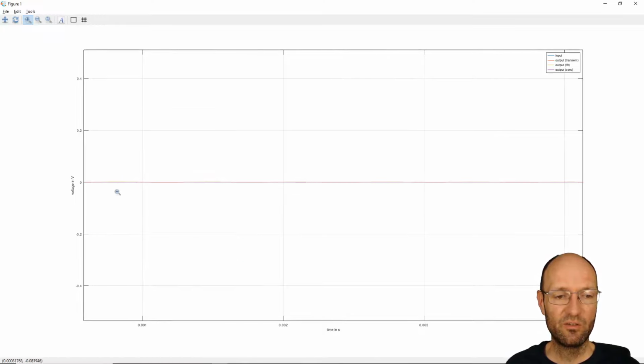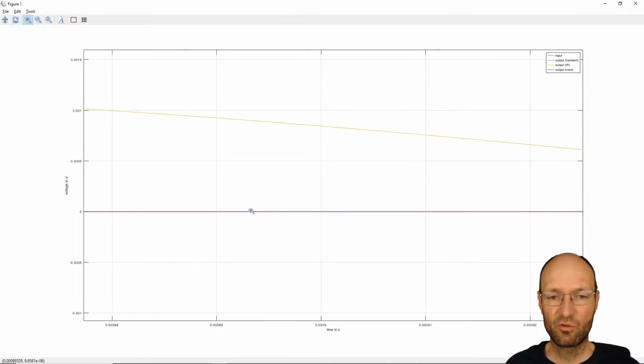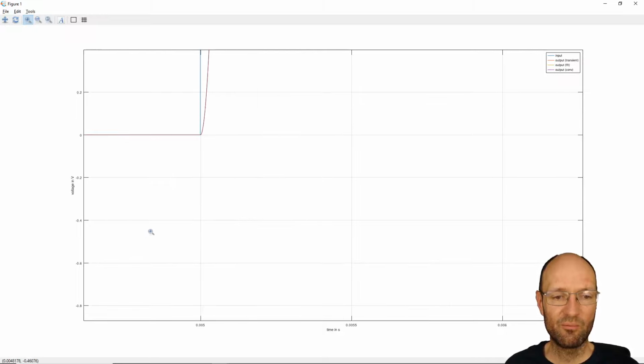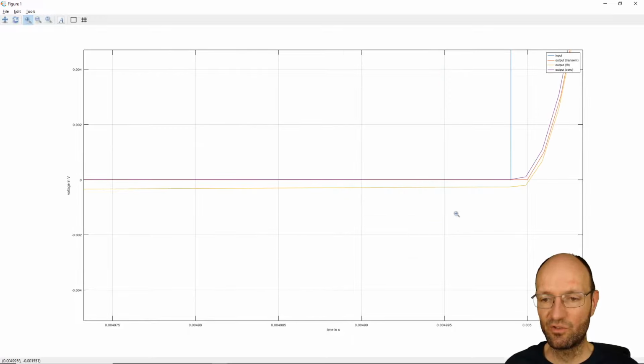And if we zoom in into this first range here, then we can see the method with the convolution also does not have this acausal or uncausal ringing problem. The convolution is also really 0 at the beginning and just starts to jump up at the place where we have some excitation here. Yeah, so the FFT solution is starting with the value of 0, but convolution and transient simulation, they really start with 0.